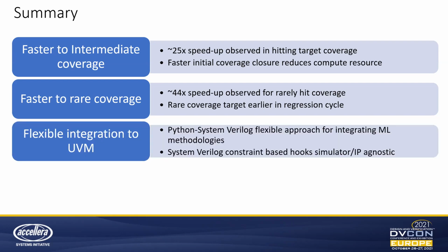This approach is also flexible. Using a Python SystemVerilog bridge, common machine learning models and libraries can easily be implemented. Directing stimulus using SystemVerilog constraints is common to many UVM or transaction-based testbenches. And the ability to direct in simulation facilitates the use of existing random test cases.